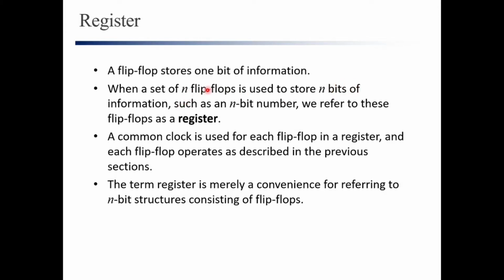So for example, if your data is 8-bit, so n is 8, so you need to have n or 8 flip-flops in order to store that data. All right, and a common clock is used for each flip-flop, means that you need to connect all the flip-flops to a common clock or the same clock signal.